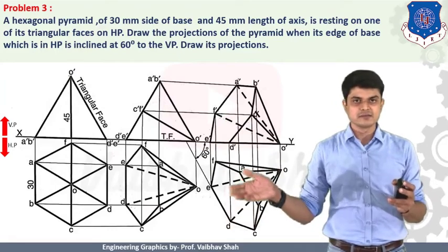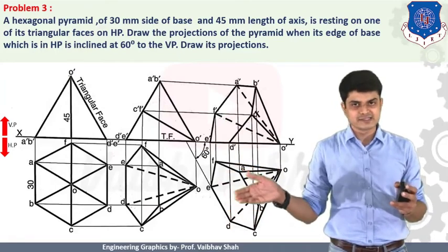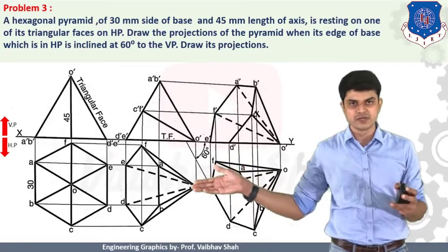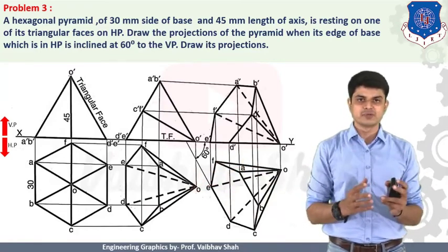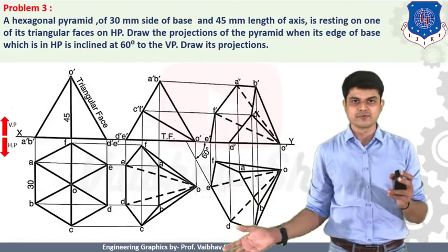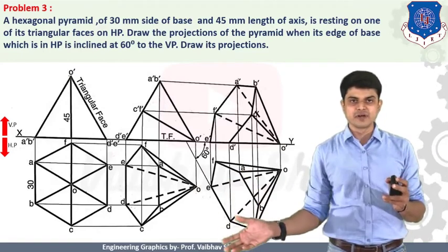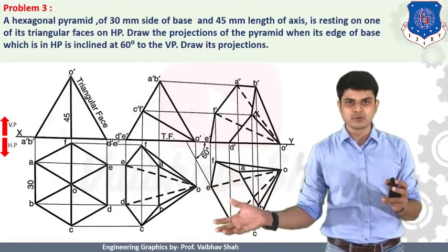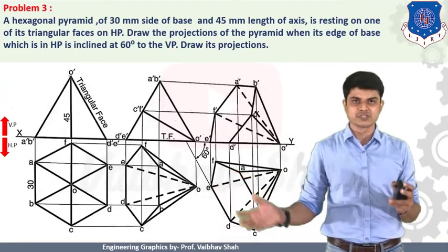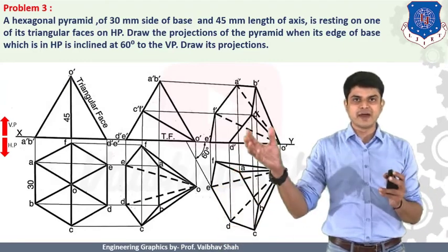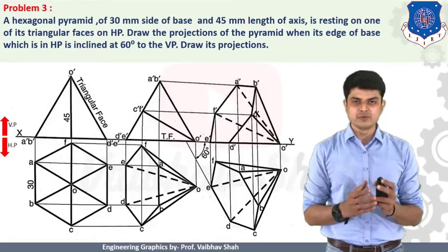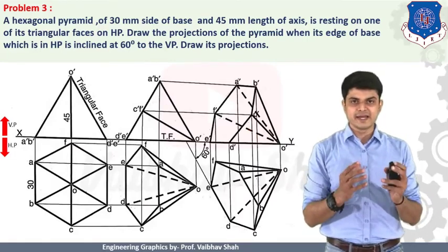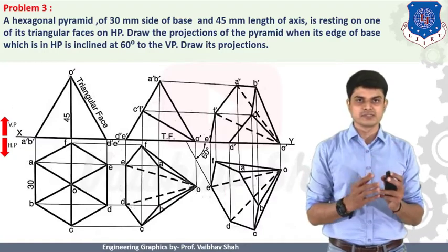We should place the edge DE at 60 degrees now, and we should redraw this figure from your second stage into your third stage. And then after, we should take its front view from this downward direction. So let us take the front view from this downward direction. So when we look and observe the object from this downward direction, we should have this final view as our projection. Now after having this final view, we should identify the dotted or the hidden portion of this part.